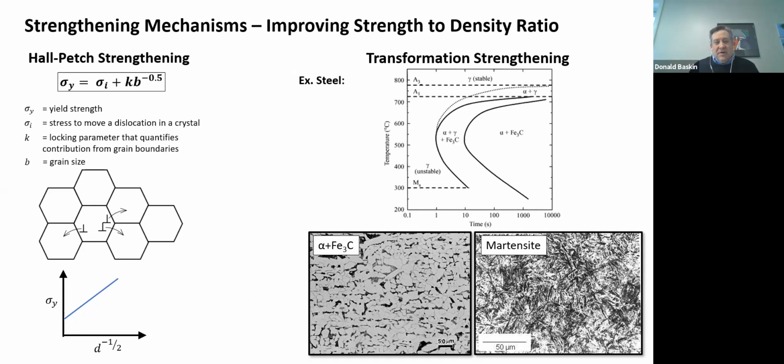because there's energy associated with grain boundaries, and materials shift in directions to minimize their energy, the grains grew, and the material was no longer strong anymore. It was back to being like normal, ordinary aluminum. So that project didn't work out very well. I think eventually my friend Brian figured out how to solve the problem with pinning the grains or something, but making small grains and preserving them at high temperatures, or even room temperature sometimes, is a challenge.